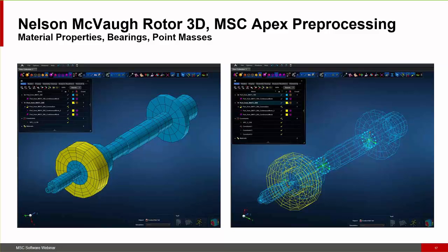So we just throw two slides in here, and you see, of course, primarily hexahedral elements representing this rotor, and then just two bearings that are shown here. We're not going to really go into detail, but there are some RBE elements that connect, and there are also CBUSH elements that are spring-damper elements that in essence represent the bearings against their counterparts. So this is just an isolated rotor on a test stand, if you will.